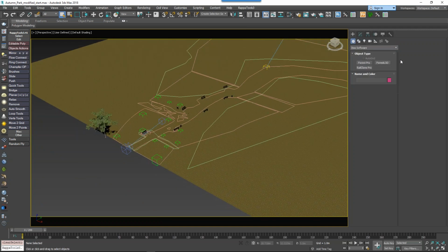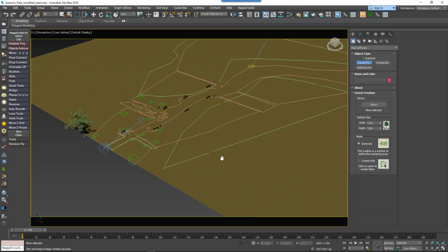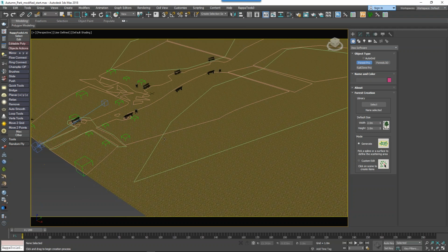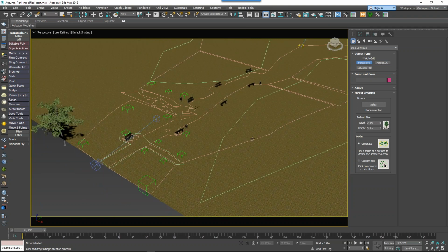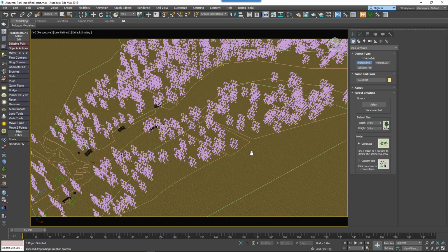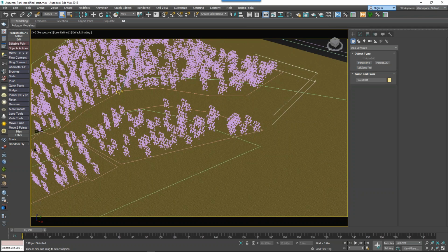So first of all, if you're completely new to Forest Pack, you'd need to know how to create one. And the easiest way is just to pick Forest Pack from the Modify panel or the Creation tab on the side here. And then you would just pick an object in the scene on which to scatter objects. Now, it could be this surface, which would fill this whole area, or in this case, maybe it's just one of these splines, and we'll create the grass first. So I would want to pick this pink spline here, which is the grass spline. But just to make sure I can pick it, I'll switch to Shape Step here. So I've got it picked up here, and I'll click it in the scene. So now we've created our first scatter, and it's really as easy as that.